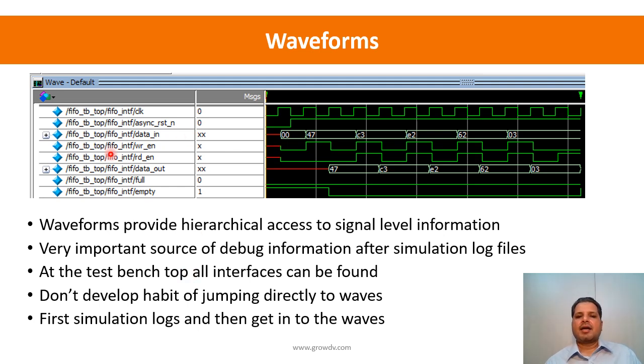right? And at the test bench top, you would typically find all the interfaces. This is very useful for verification engineers, so you can add the whole interface in one shot. See, this is the benefit: if it was Verilog, we had to go and pick all the individual signals to look at them, but here we can just drag and drop the interface, and we can look at how the activity is taking place within the interface.